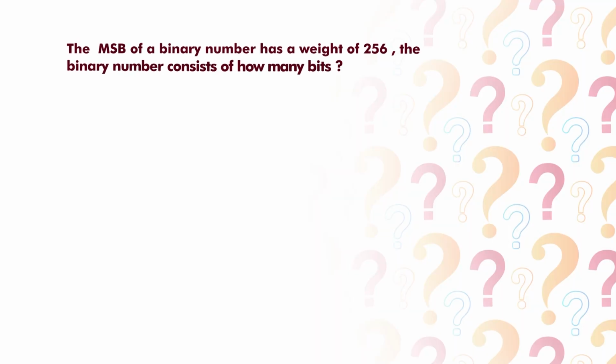Similarly, at time instant t3, you can see that it is at level 4, that is between 3.75 to 5 volt, but seeing the voltage at time instant t3, I will choose it as 5 volt. Similarly, at instant t5, you can see that it is at level L2, that is between 1.25 volt to 2.5 volt. So, as it is nearer to 2.5 volt, I will choose its value as 2.50 volt.